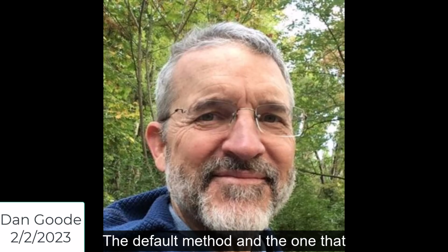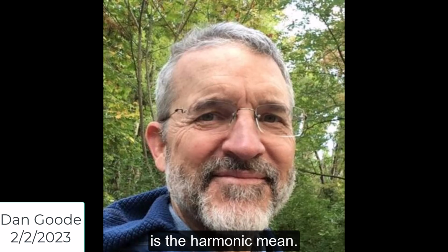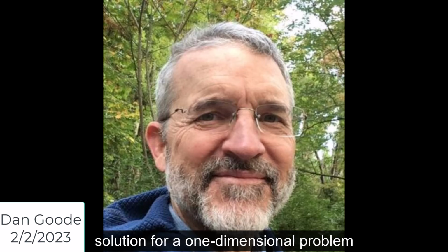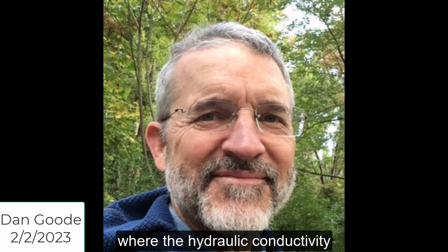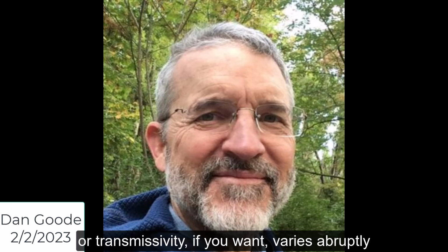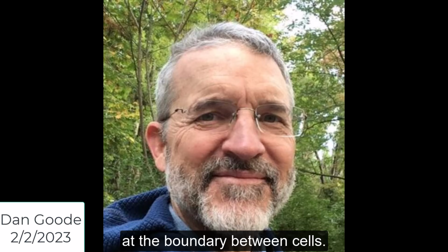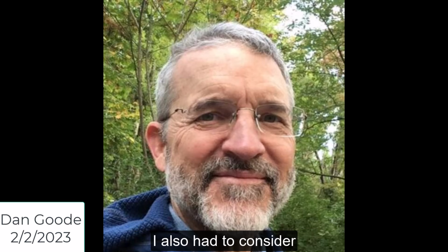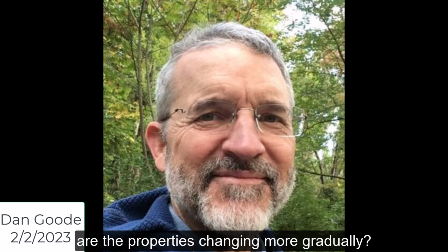Well, the default method, the one that practically everyone uses, is harmonic mean. You can demonstrate that that's the exact solution for a one-dimensional problem where the hydraulic connectivity, or transmissivity if you want, varies abruptly at the boundaries between cells. And when I was doing the particle tracking and thinking about it, I also had to consider where the properties change. Are they changing abruptly at the cell boundaries, or are the properties changing more gradually?